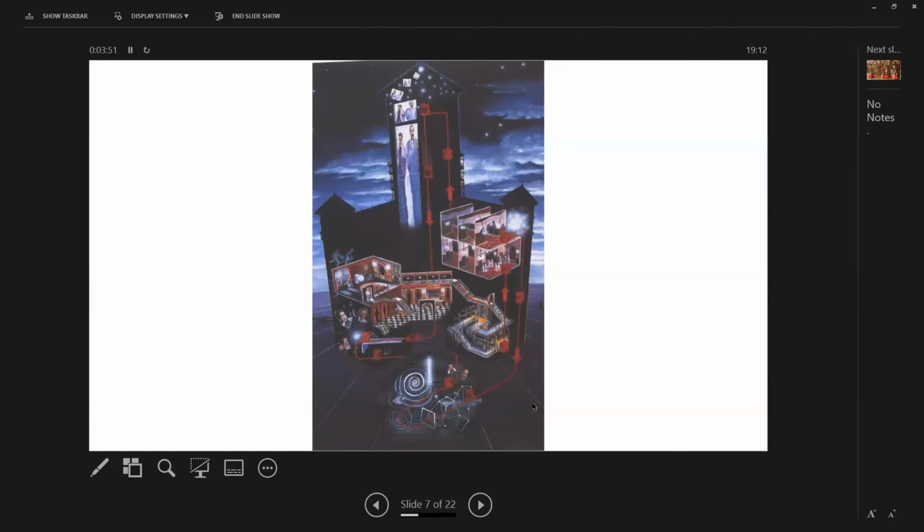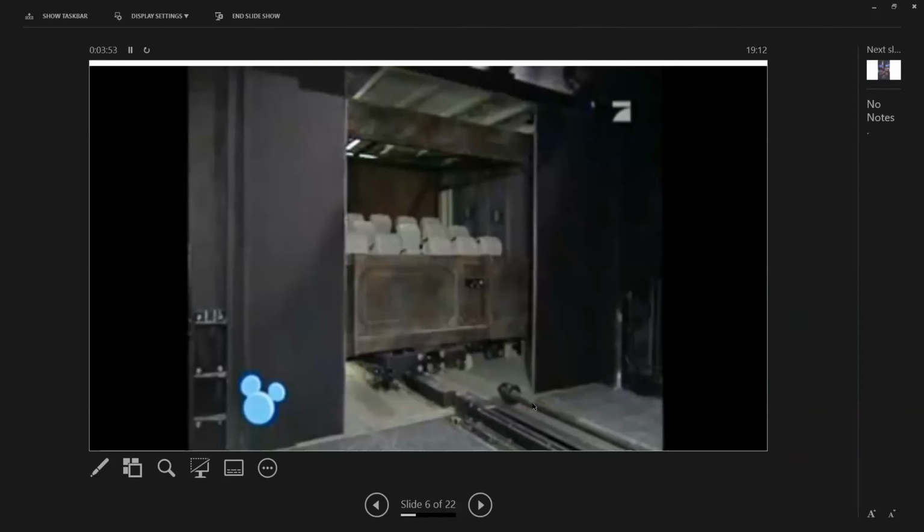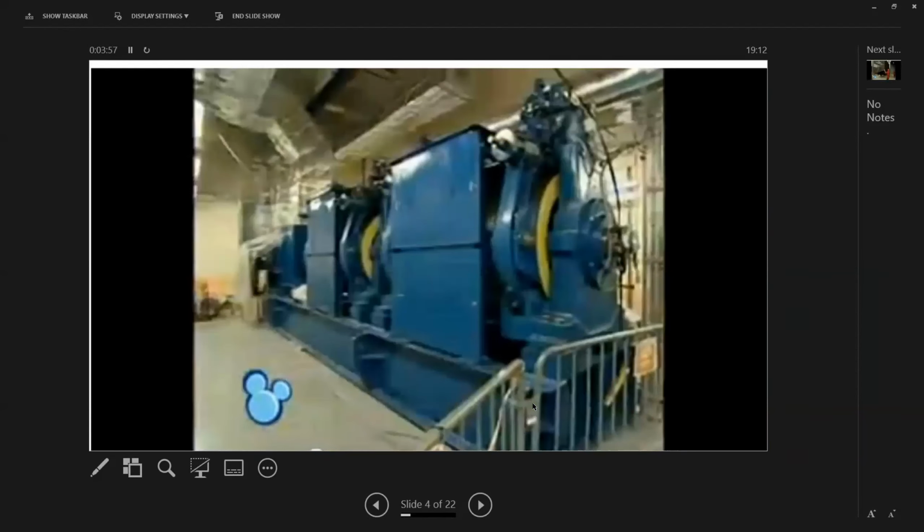The drop elevators, the 2 gigantic controlling motors, are 12 feet tall, 35 feet long, and each weigh 132,000 pounds. And again, they can move the car 39 miles per hour. So these variable speed drives use PWM, and that is what begins to cause the problem.